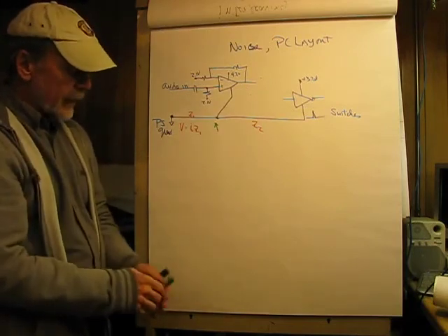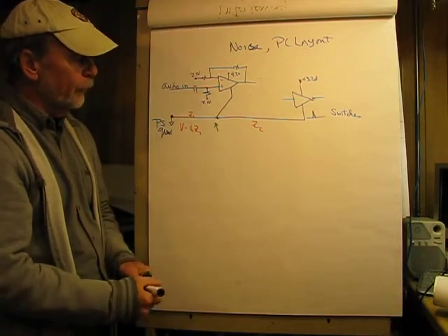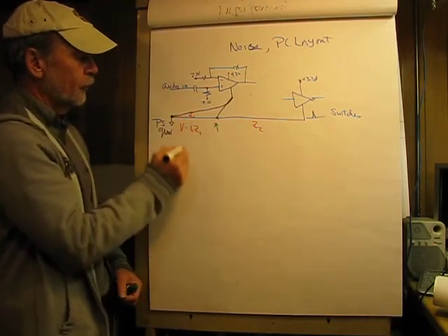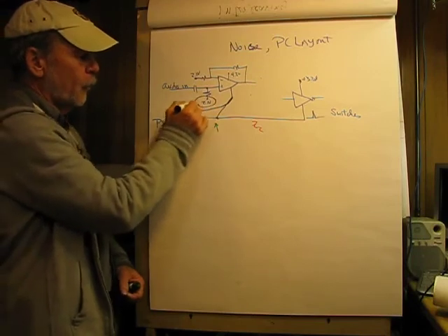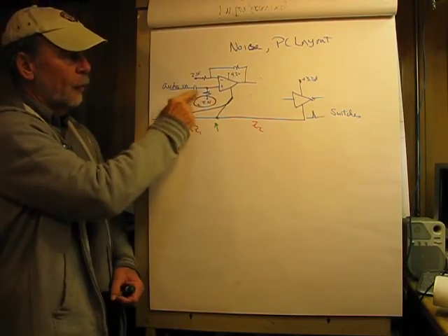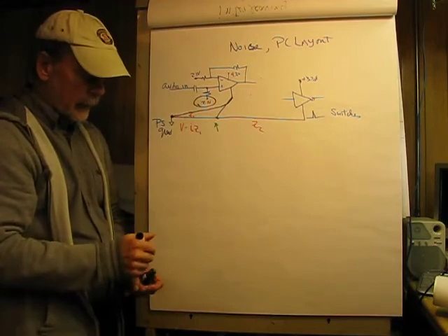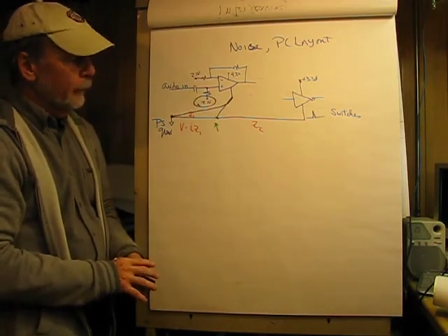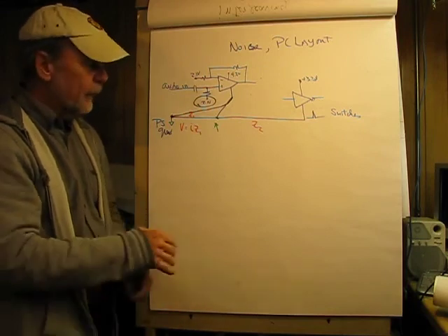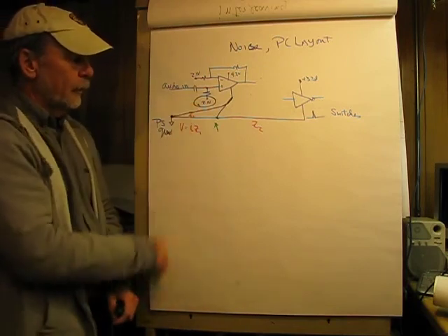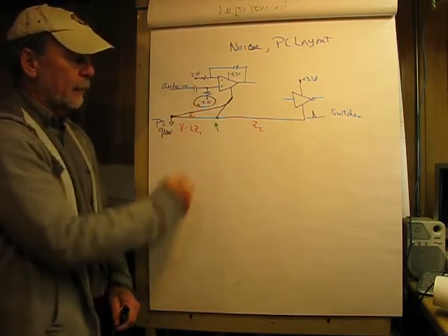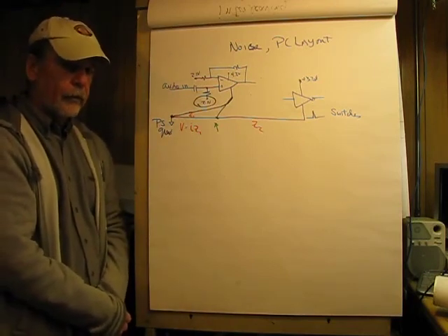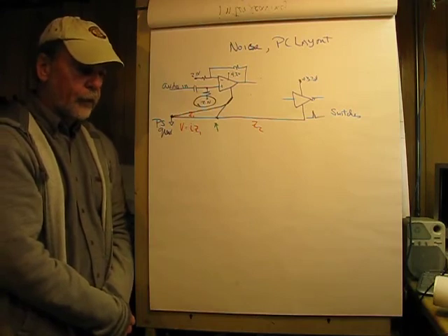So when you lay out PC boards with noise like this, the correct way to do that would be to return this to the star ground, and this point here, which would be the bias point, the 50% point, and if you've had Electronics 1, that would be the ground potential because you're negative and positive. Also has to be very clean. So this is a very common source of noise voltage in PC layouts, referred to as a ground loop.